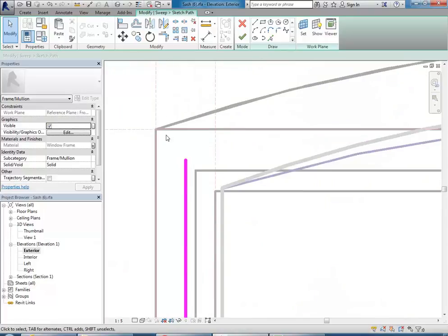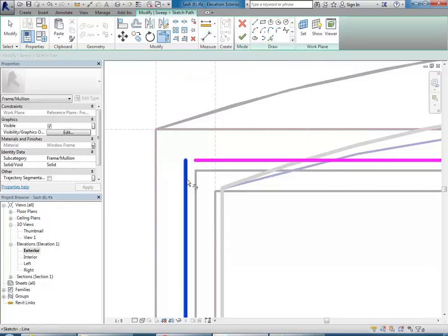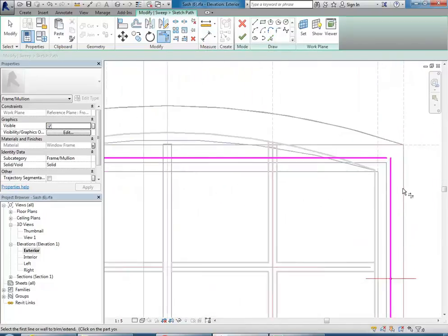I'm going to use the same distance as they have over on the left here, so I'm just going to measure that. So it's 10 mil. Okay, so when I go to pick lines, I'll need to put a 10 mil offset there, and the lock option gets grayed out. I can't have this locked by default. So I'm just going to set that out first, and I'm going to trim them right away.